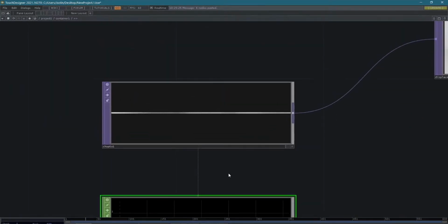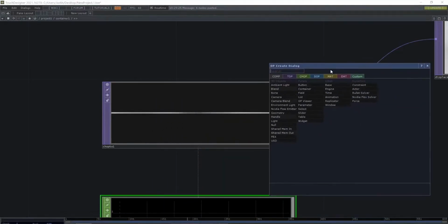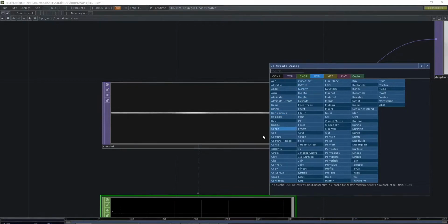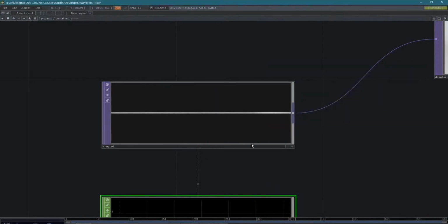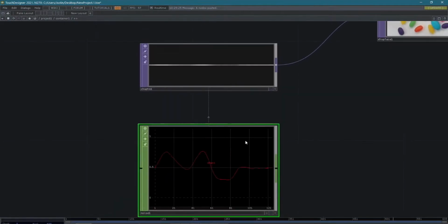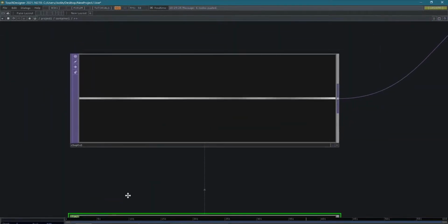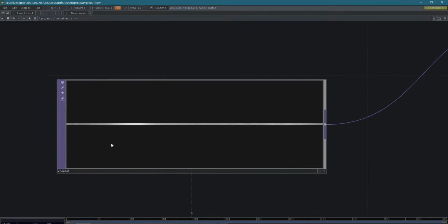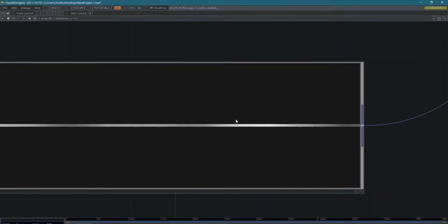And so what we're doing here, and this is the fun thing about TouchDesigner, is numbers don't have to stay numbers. You can turn numbers into textures. You can turn a 3D shape into a numerical list of the points that make it up. So what we've got here is our first type conversion. We're taking this noise channel operator that's creating random numbers between 0 and 1, and we're turning it into one row of noise with a CHOP to TOP. And you can see that those random numbers are mapping out between 0 and 1 as white to black.